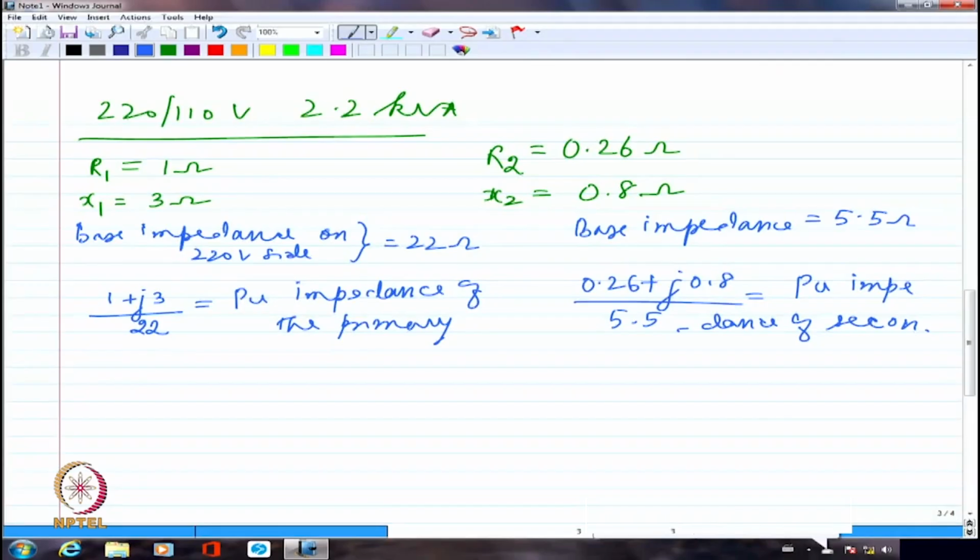Because we do that, again we are able to get an estimate whether the voltage drop is less than 10%. That means whether I have done everything correctly or whether the transformer is good enough. All these things I would be able to get a feel for by observing. That is one of the major advantages of using per unit notation.